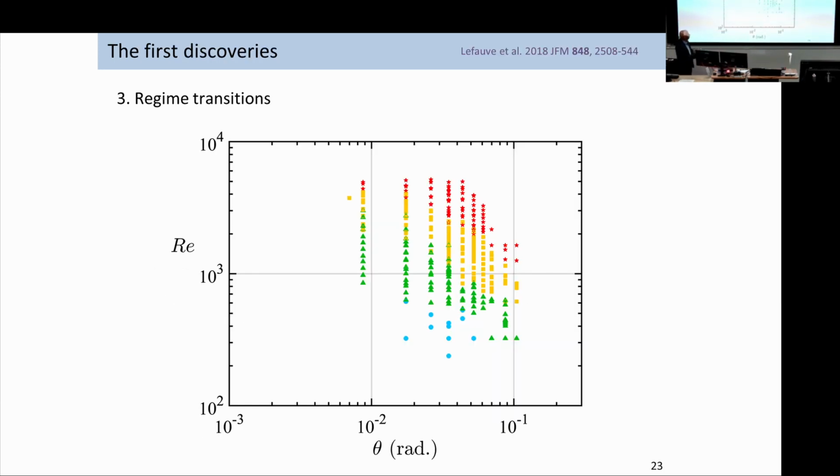Anyway, so how do you characterize these regimes? We've taken the previous schematic, plotting the actual data in log Reynolds number versus theta. We find that those regimes, so laminar, waves, intermittent, turbulent, seem to scale on theta times Reynolds number equals constant. These are the 2 parameters we have. And we want to try and explain why that's the case and how that works in the system.